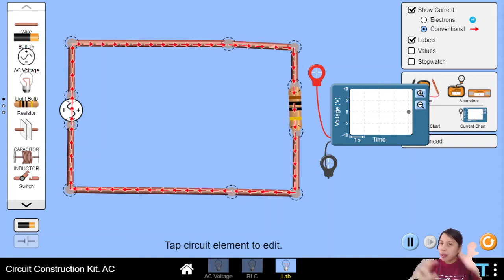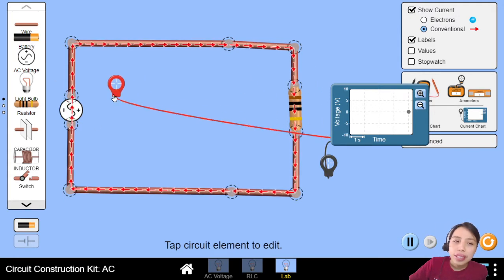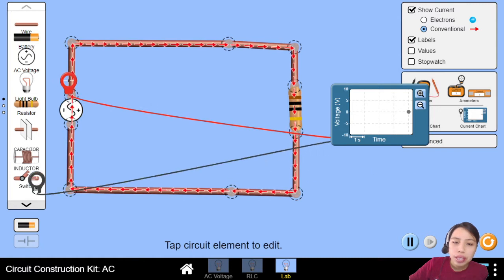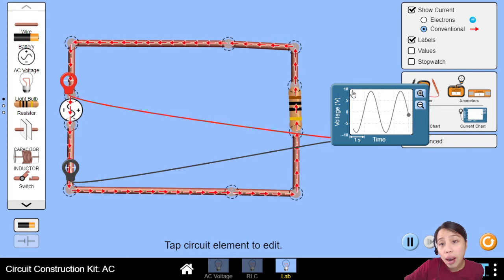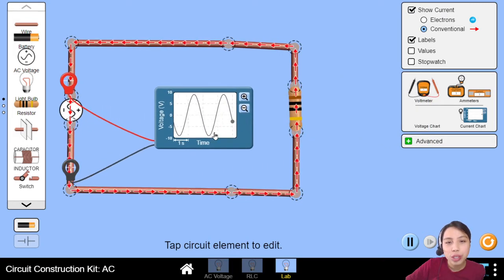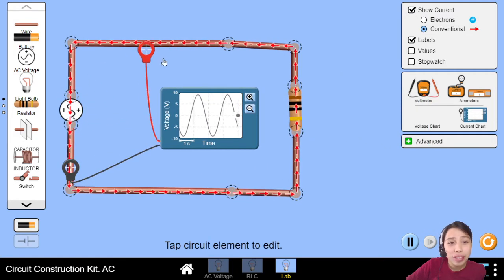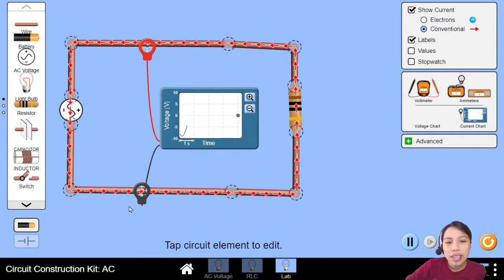Up to this point, you have looked at what AC is and how the current looks, such as this simple circuit where I connect an AC power supply to, let's say, a resistor. So we can see that the AC power supply is going to cause an alternating voltage, which you can see on a device like a CRO, like this one. So make sure when you do experiments, you want to measure voltage of AC or frequency, use a CRO, because that's the one that will give you this nice oscillating kind of pattern.